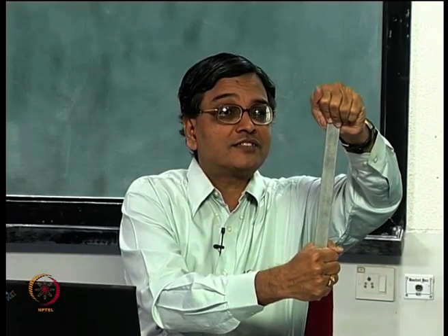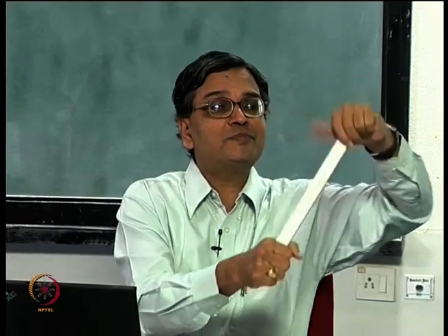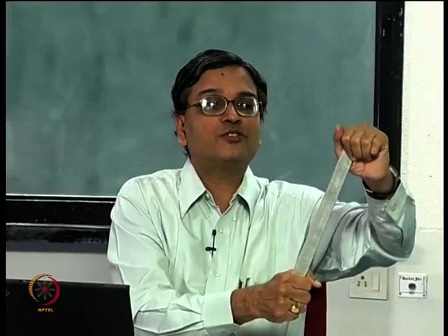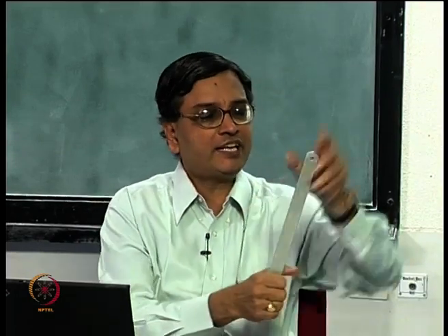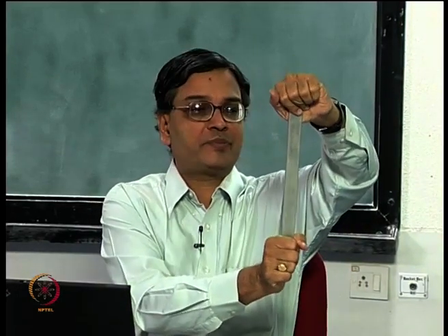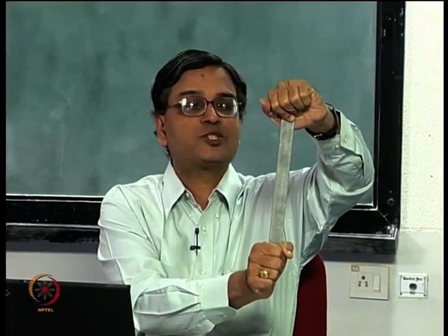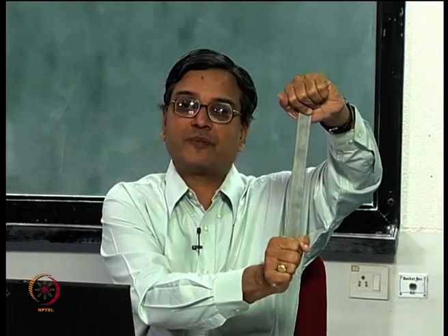Where are 6 components? You are only saying only 1, and what you have in this simple example problem is, stress is a tensor of rank 2. So, you have 9 components. Of the 9 components, because of symmetry, you have only 6 independent components. So, in a simple tension test like what you do on a slender member, you evaluate stress and it appears to be a scalar, P by A appears to be a scalar, and that is what you have learned in a simple course in strength of materials.